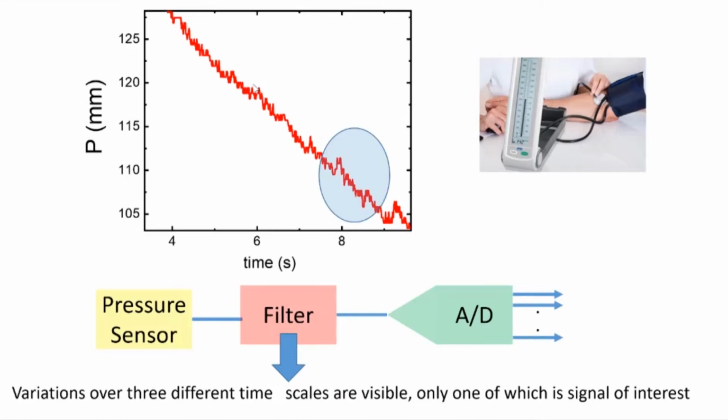A resistor responds instantaneously to every signal, V equal to IR. If V changes, I changes instantaneously. But capacitors and inductors don't respond instantaneously. They have a time response. So they are very useful for implementing filters, and so they become essential elements.